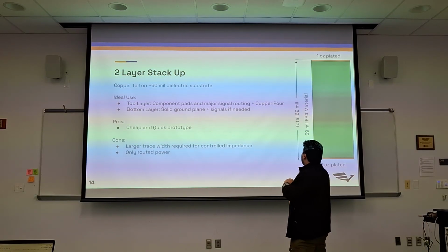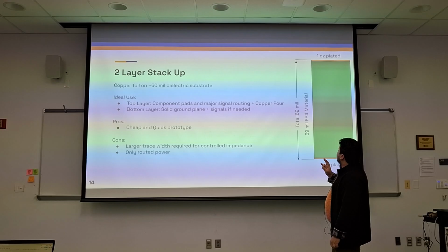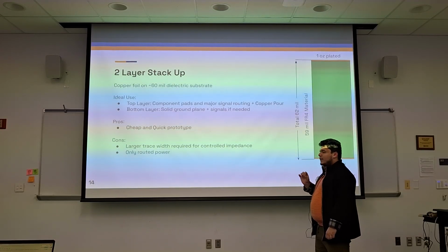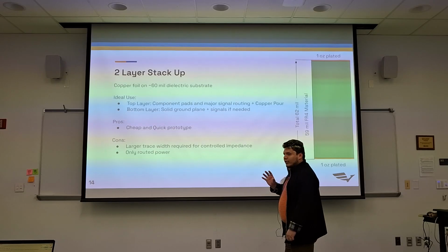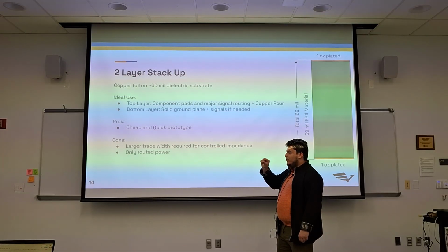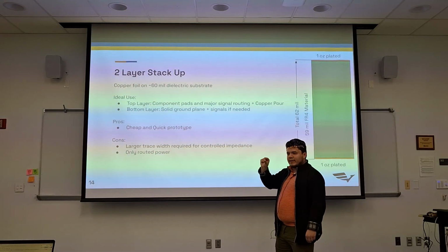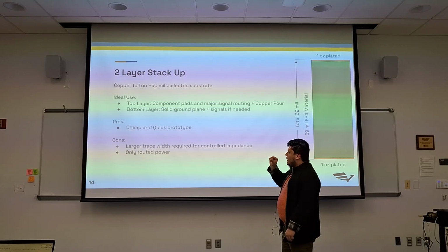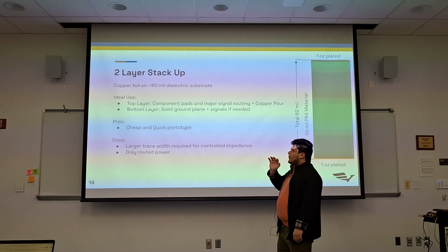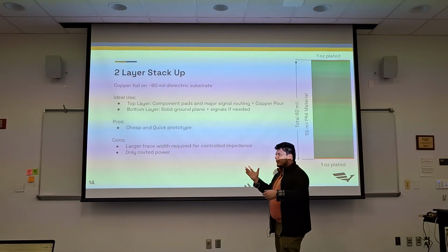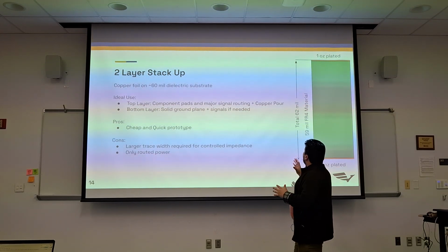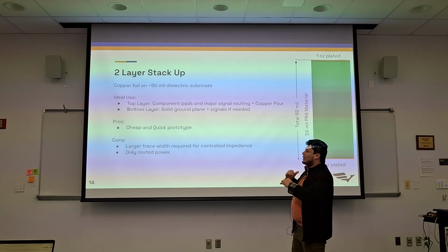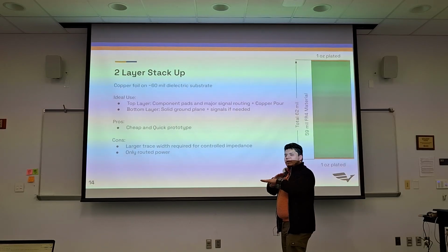And so I mentioned this because when we're talking signal integrity and making sure that we are controlling our impedances, that assumes we have a very controlled and set thickness to the copper. However, generally, and this is just best practice in industry, doesn't affect us too much, you want to make sure that your controlled impedances are 100% solid.